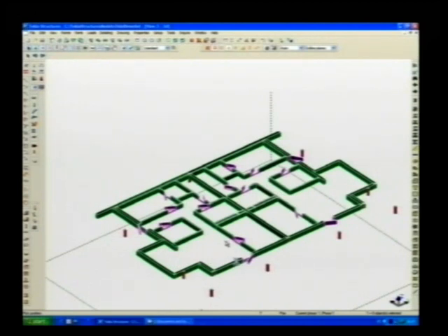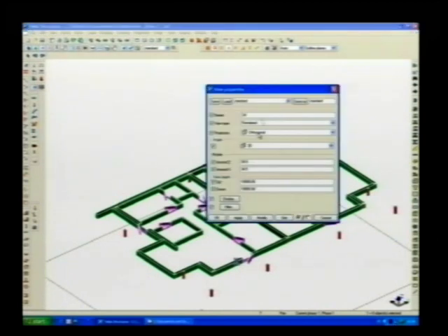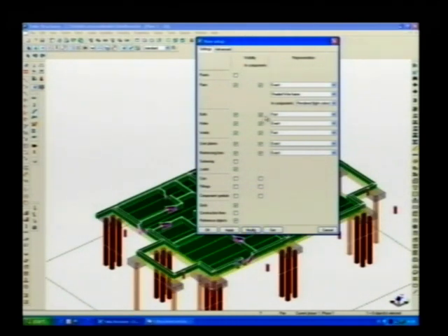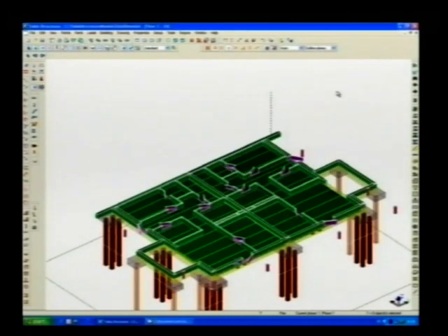With the clipping plane, I can spatially adjust the viewing depth. I can have several clipping planes if I like. The structural designer can carry on the design by adding structural elements and details into the model. Isn't this a revolution? Isn't this the way we should be designing? Who's drawing lines just to trace? We're designing now. This is getting very close to design.